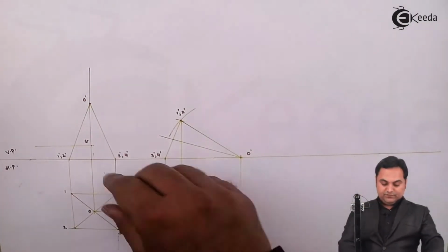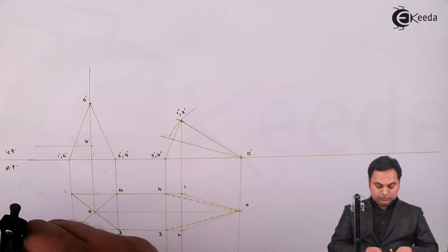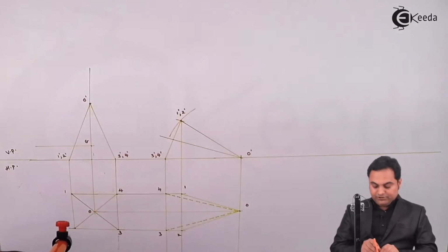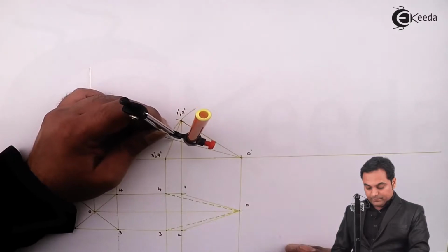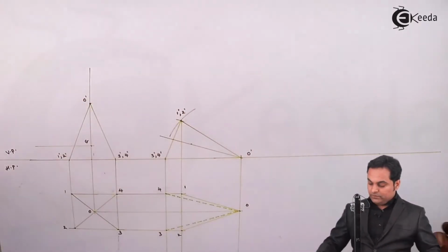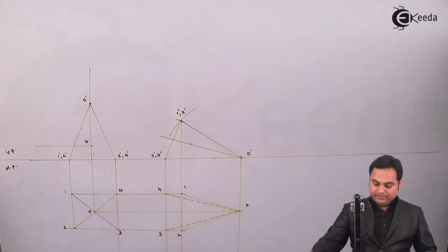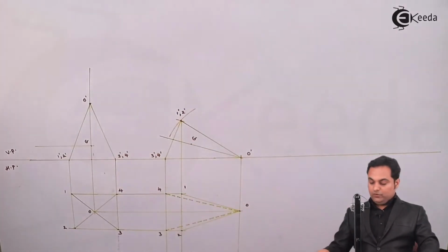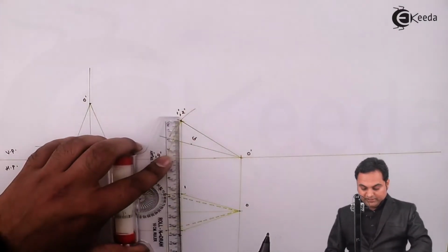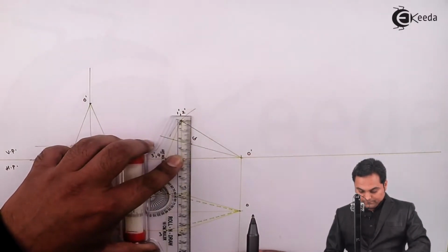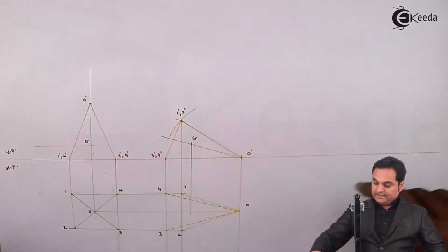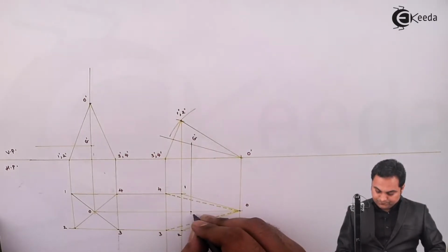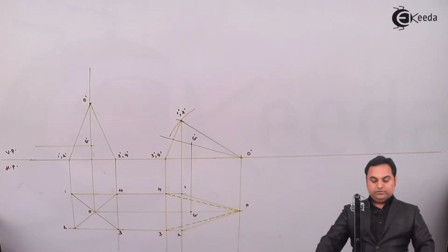Now this CG of the square pyramid, I locate it in the second condition as well. So from the base, I am measuring the distance up to point G. So from the base up to point G, here I am getting the center of gravity of the square pyramid. Next, this center of gravity will be projected in the top view. For that, we require a light vertical line. And here we are getting the CG as point G in the top view.